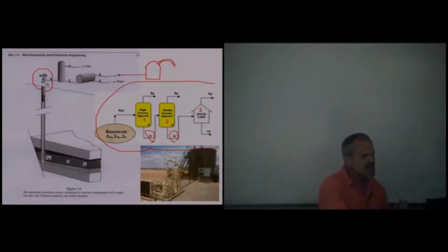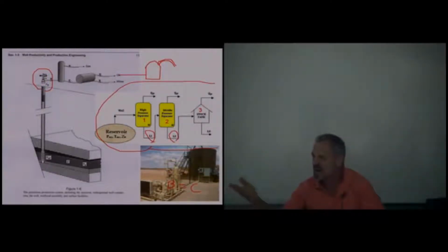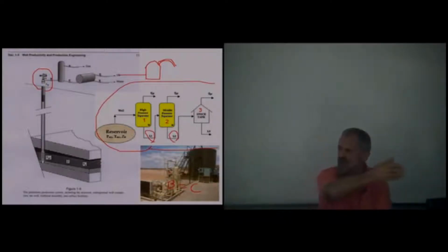Revenue, except I can tell you right now that down here, benefits equal cost. You spend about as much money on a vapor recovery unit as you do to put the gas back in there. But you'd run this vapor recovery unit even if you were losing money. And why? Emissions, regulations. And methane is worse than CO2 as far as a global warming gas.